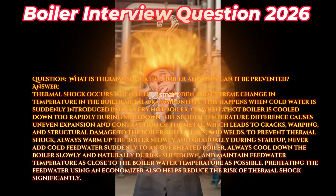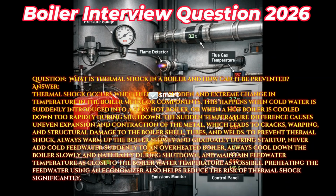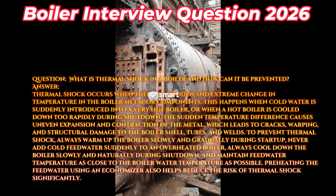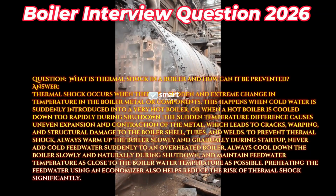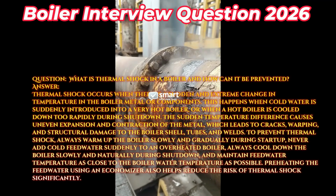Question: what is thermal shock in a boiler and how can it be prevented? Answer: thermal shock occurs when there is a sudden and extreme change in temperature in the boiler metal or components. This happens when cold water is suddenly introduced into a very hot boiler, or when a hot boiler is cooled down too rapidly during shutdown.